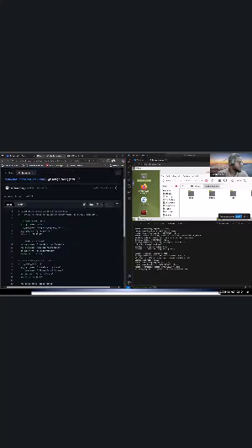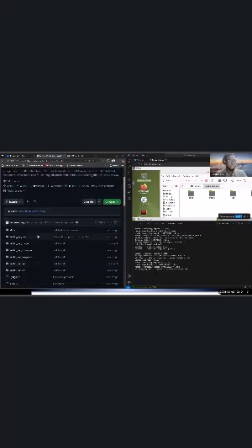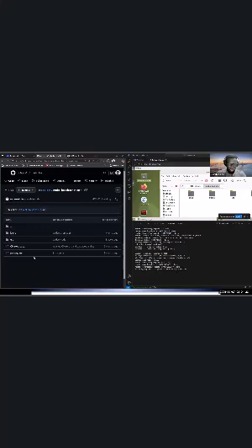All right, config: you can see the configurations, which use the Gazebo bridge. And then the code. I know there are a lot of folders and a lot of structure, but trust me, you just have to take it step by step. I'll talk through the basic things you all need to understand. The description is what we call URDF, Unified Robot Description Format. URDF is the first thing you need to do in building a robot. You have to have the description of the robot.